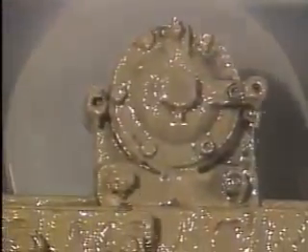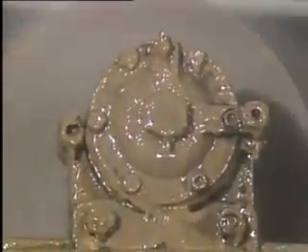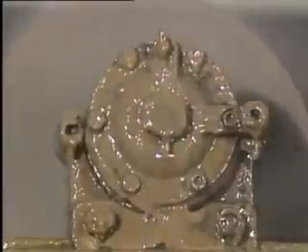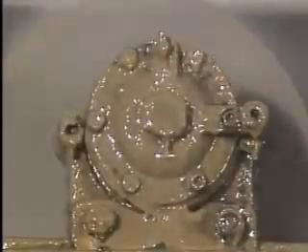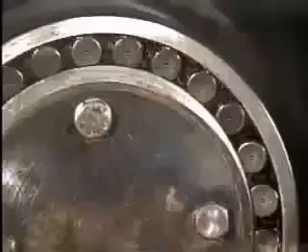Additives can also protect against corrosion due to contact with water. This bearing housing is constantly exposed to hot water vapor. Water works its way into the bearing and contaminates the grease. To keep the water from collecting in pockets in the grease and corroding the bearing, a water-stabilized grease is used. Although water and oil or grease normally don't mix well, an additive in the grease used in this bearing makes the water and grease mix thoroughly. This thorough mixing prevents the formation of water pockets that could corrode the bearing.